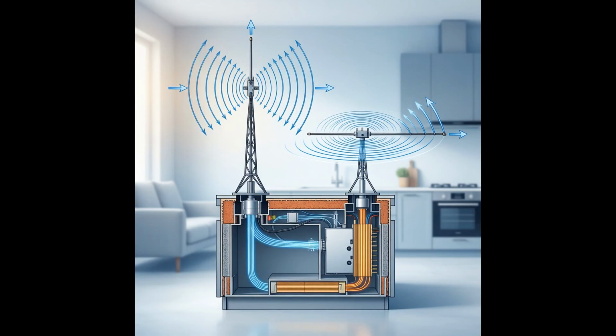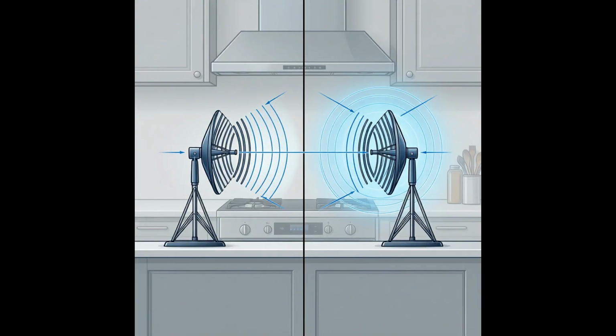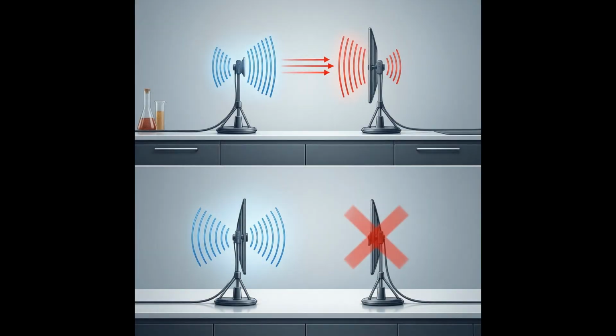Consider two dipole antennas where one is vertical and the other horizontal, creating a 90-degree misalignment. This orthogonal configuration blocks nearly all signal energy regardless of distance or transmitter power output. Even slight angular deviations reduce coupling efficiency by converting usable wavefronts into reflected interference patterns. Understanding polarization constraints leads us to examine how router placement geometry further shapes signal distribution patterns.